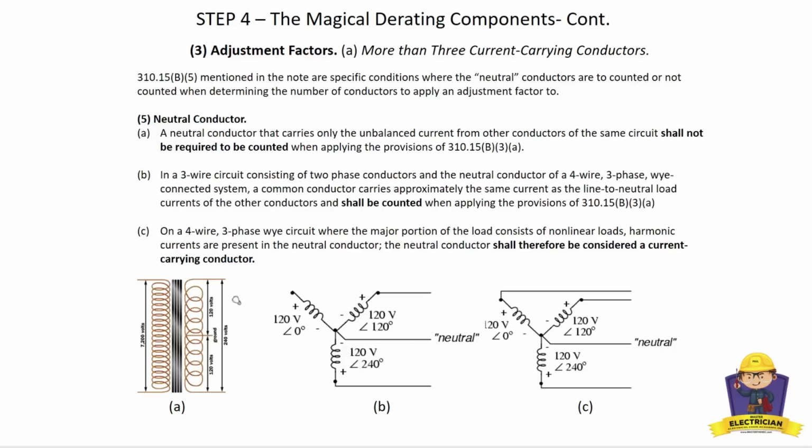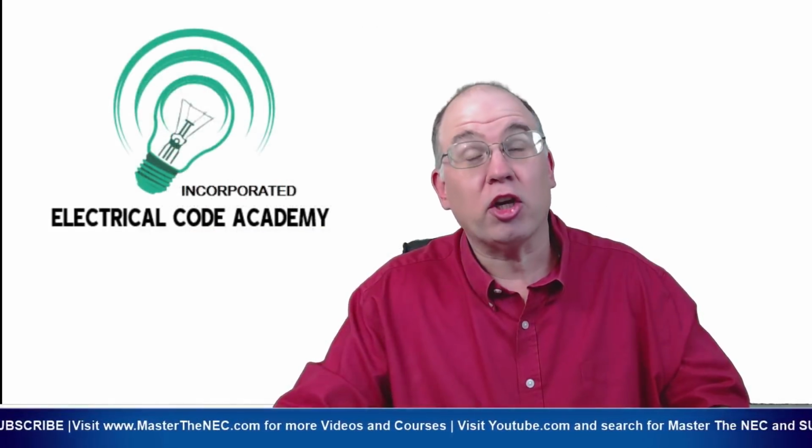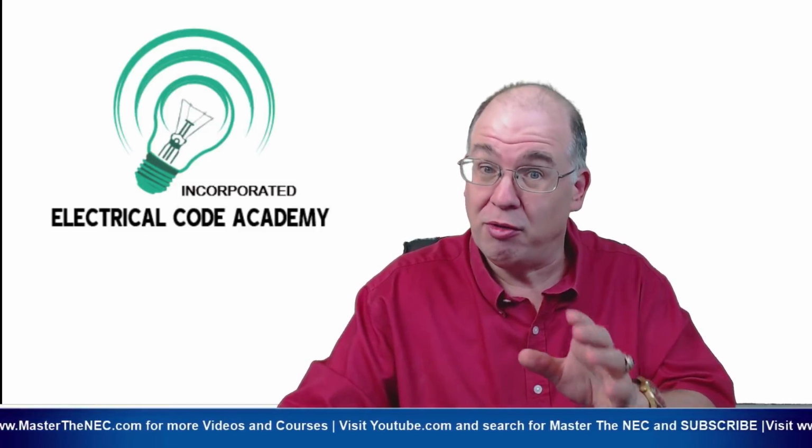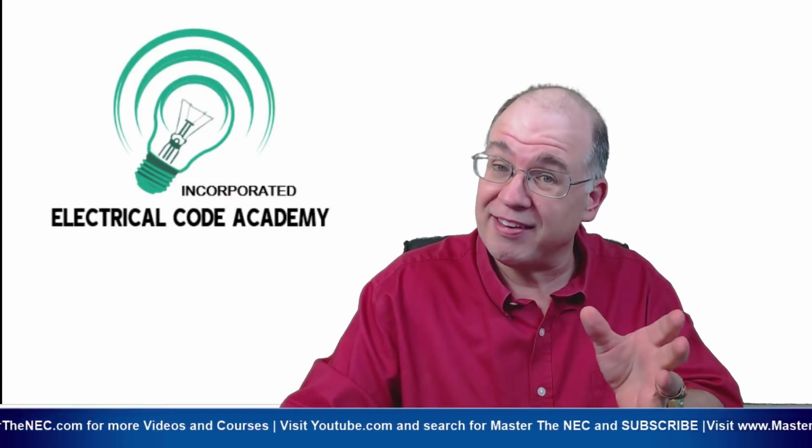So this is a typical, let's say, residential transformer from a pole. It's dropping down. You have two hot conductors, leg A, leg B, and you have a grounded neutral conductor. It carries the imbalance between these two phase conductors. So it does not have to get counted. Now, in a multi-wire branch circuit, if you install that multi-wire branch circuit correctly, and that's important, if you don't know what a multi-wire branch circuit is, then this isn't the video, or you maybe need to go back into our basic video.